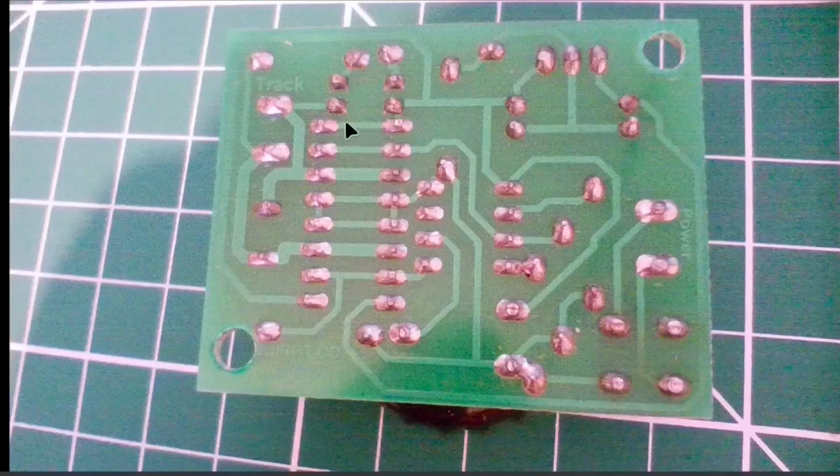So this IC looks to be a driver of some sort, and you can tell that by the thick tracks, because they're going to be passing more current, and it's also connected directly to the output. So that is a driver. I originally thought it was sort of a quad pack of transistors just to drive the output, but I'm getting ahead of myself here.